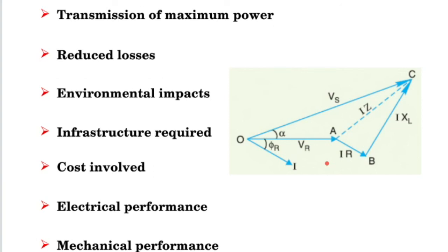Reactive power means megavolt ampere reactive, MVAR, that we calculated in the previous tutorial. Now, as the transmission line circuit consumes MVAR because of the inductance present in it, who will supply that MVAR?